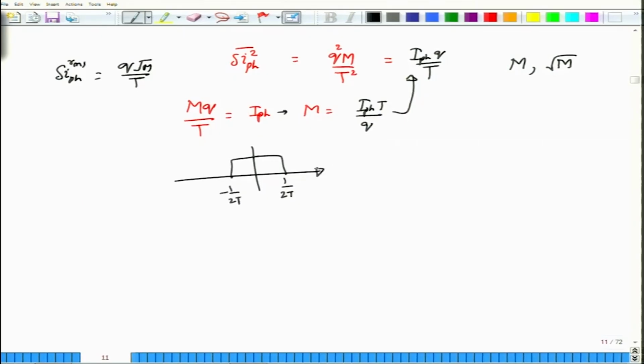This is the baseband bandwidth that we are talking about, which is perfectly valid in this case, because the signals, once they have been converted from the optical domain to the electrical domain, are now centered at the baseband level. They are centered at 0 frequency.